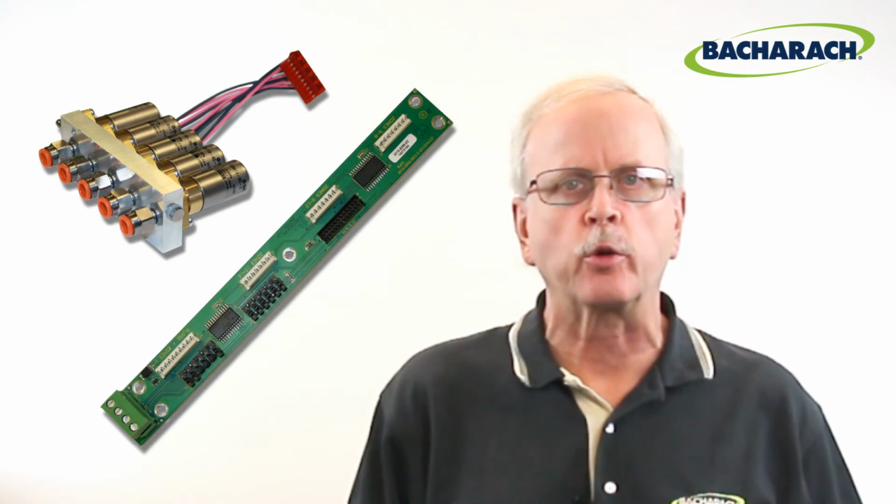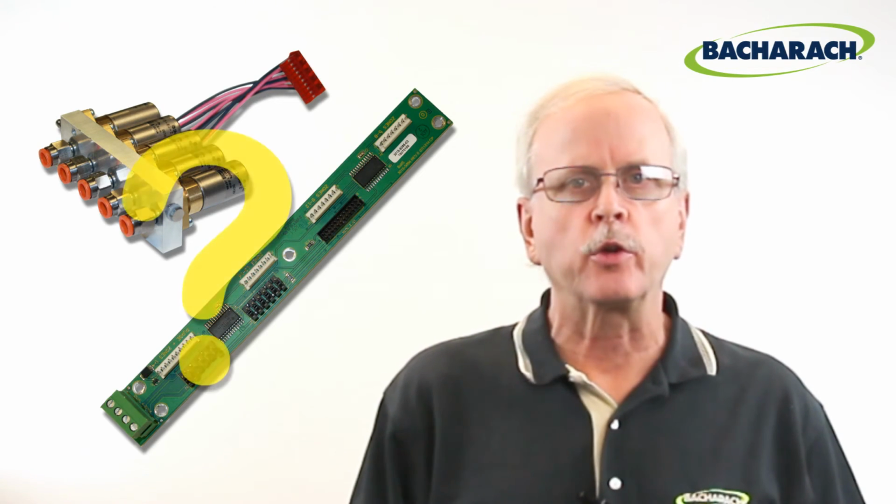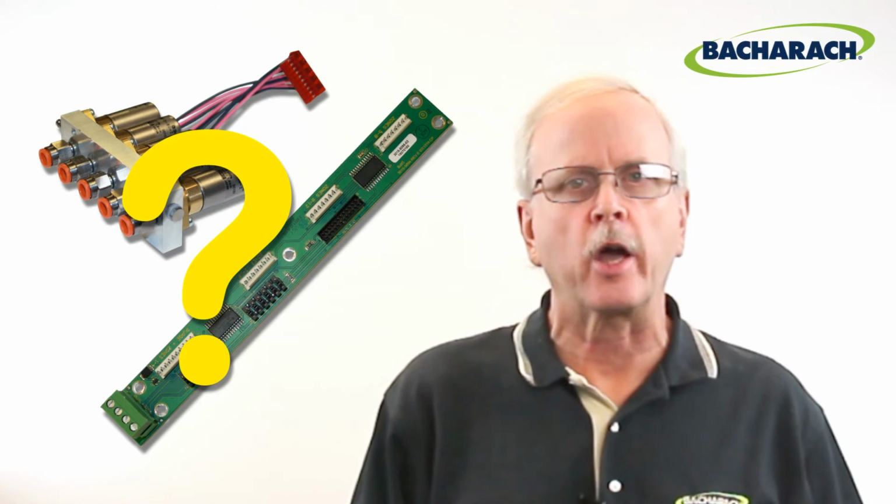If removing the suspect zone sample tubing did not diagnose the problem, the no-flow zone fault is likely being caused by either a mechanical issue related to the solenoids in the manifold assembly or an electrical issue related to the printed circuit board that drives these solenoids. In each of these cases, you will need to continue your investigation to diagnose further.